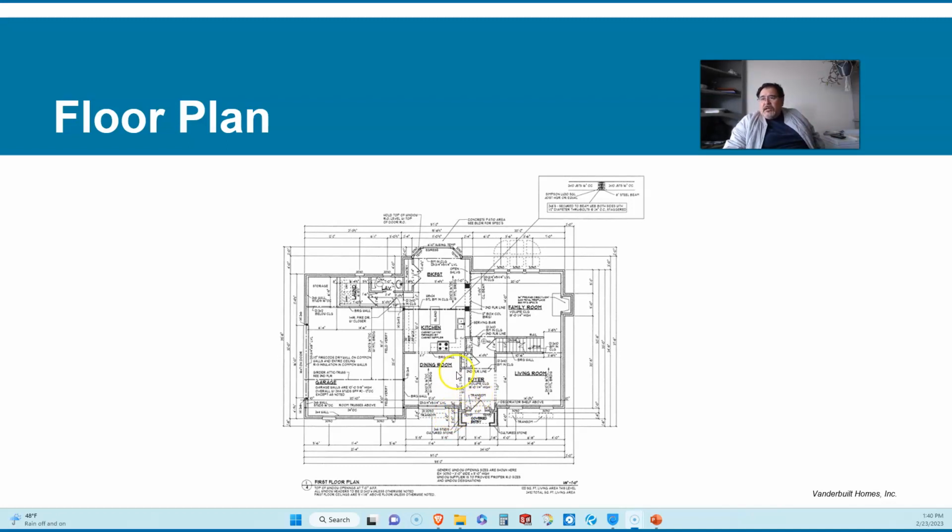You see these dotted lines that are in line with these walls. They can be overhead support structures. They're definitely hidden lines because they have dashed lines. So it's an object not at the same level as these locations of the walls. So they're either overhead or down below.